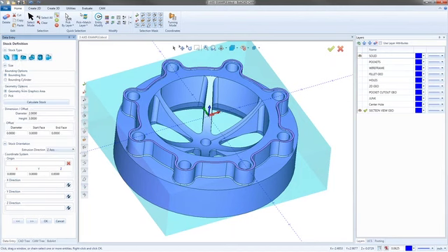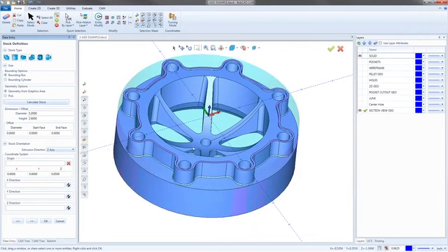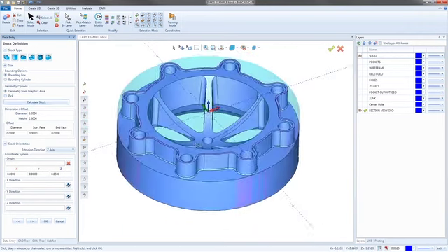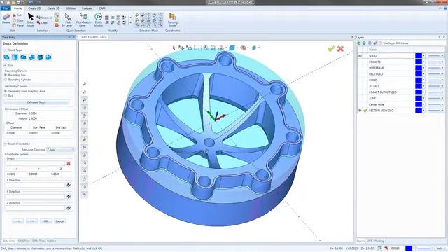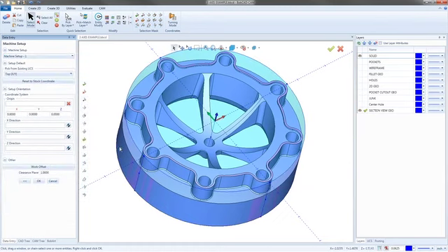And what you'll see is the preview doesn't automatically update super quick like we have right here. So what you could do is you could say calculate stock and then just give it a second. This is a pretty intricate model. And now that it's calculated, it'll create that stock on there. And then, pretty much from there, I just want to scroll down and hit the forward option. And this is where we get to set up our origin.